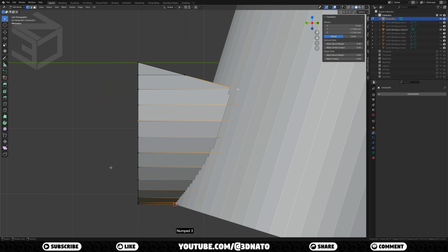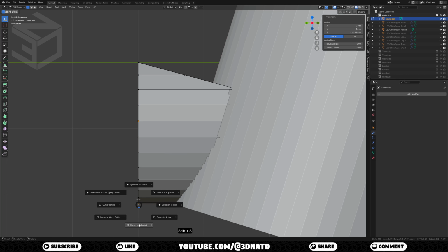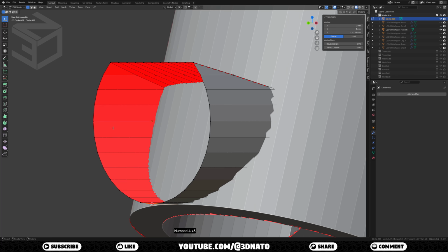On the left view, select this bottom wrist vertex, press Shift plus S to snap and select Cursor to Selected. While still in edit mode, press Shift plus A to add and create a mesh circle. Set vertices to 34, radius to 2.16 mm divided by 2, add the radius to the Z location and set the X rotation to 90 degrees.